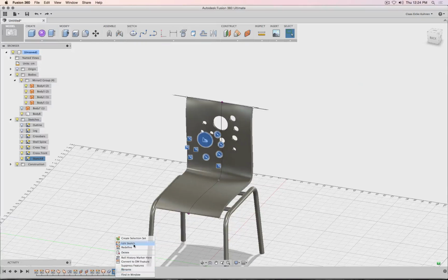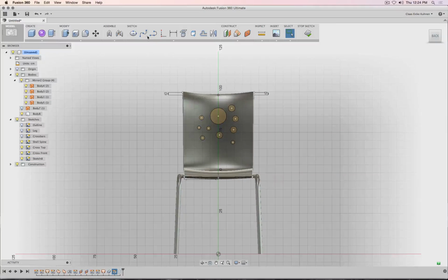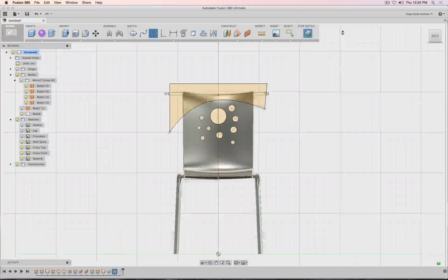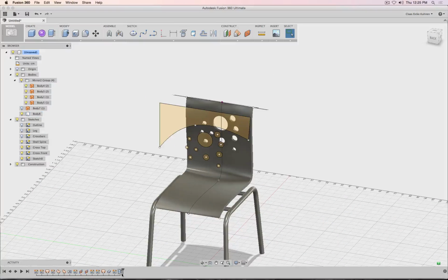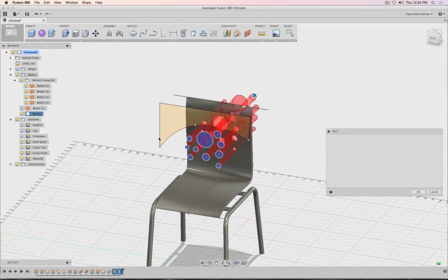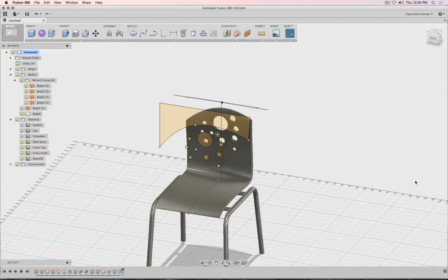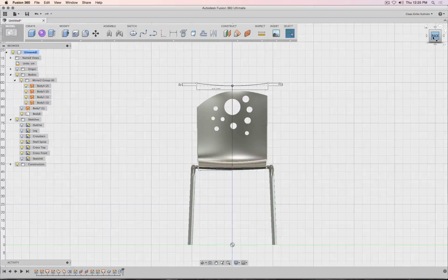Okay, and this sketch, for example, I go into Edit and I'm going to take a spline there and there. Let's say maybe an arc like this. Okay, and I have to create a solid piece, kind of like in Revit they call this one a void geometry. So this part now I can extrude as well. So I add it and add this one to the cut geometry. And here you see this way then I actually cut out or trimmed the top part.